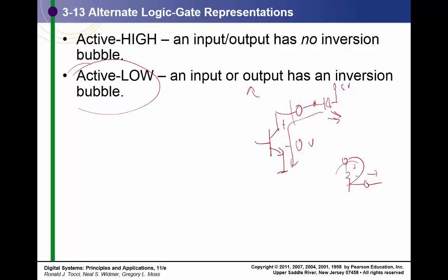Quite often you'll hear the term open drain because you're talking CMOS. Here we're talking TTL, so it's open collector, where we supply the ground. So if we want the LED to be on, the motor to spin, or whatever, we will use an active low. Active high means that we supply the current.